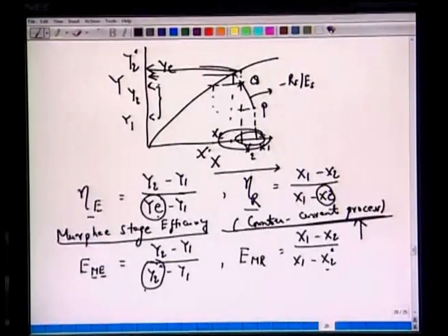There is one small thing here: so far we have worked with flow rates. Two streams are brought in contact either in a stage or in a continuous contact process, co-currently, counter currently, or cross currently. It's also possible that we have a batch system. If you recall from your kinetics, reaction engineering, or some stoichiometry, now we are talking of two streams or two immiscible liquids, L1 and L2, brought in contact, and we mix them perfectly. So there is no flow rate here.